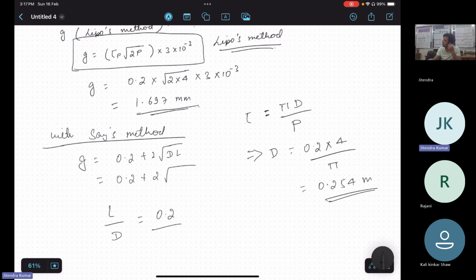Since induction machine we are considering by default as a radial flux machine, right? In a radial flux machine, diameter is more. L by D ratio, not D by L. Okay, L by D you were saying 0.2. Still, it is too high, but anyway, it is considerable. D by L is almost 5 times, so diameter is almost 5 times the axial length. So L we can calculate as 0.2 into